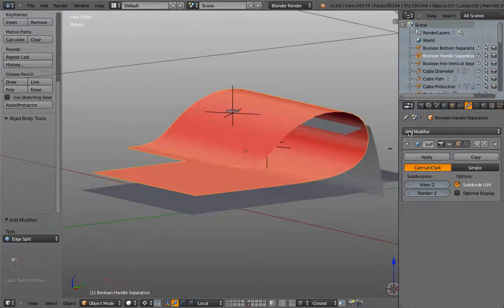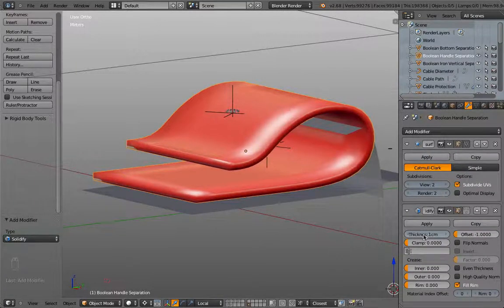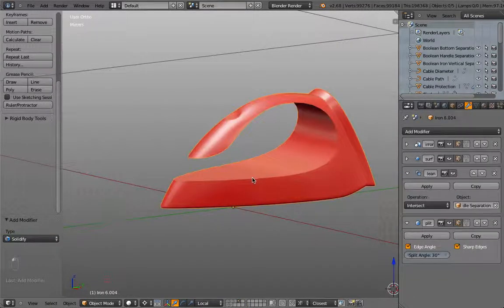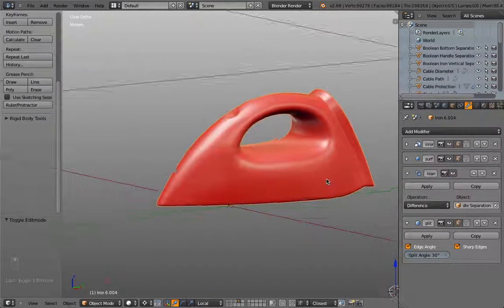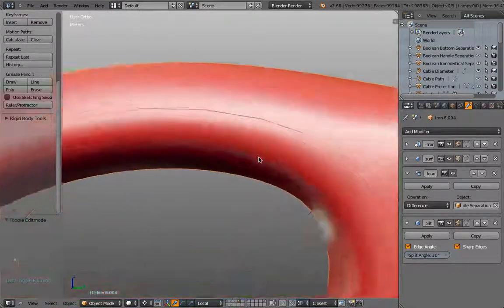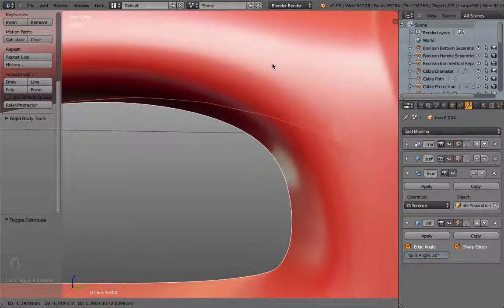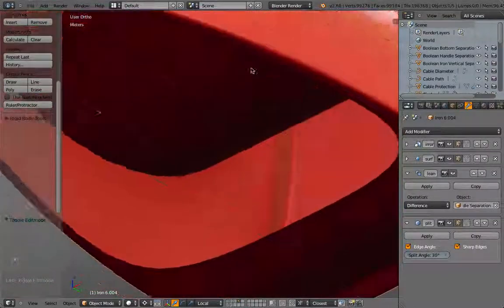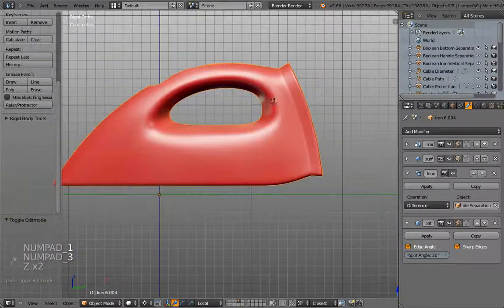But what I do now to this shell, I give it actually a small thickness. Some 0.1 millimeters maybe. So really, really thin hairline. And instead of intersect, maybe difference. And you can see there's actually the separation. Okay, so with this done,